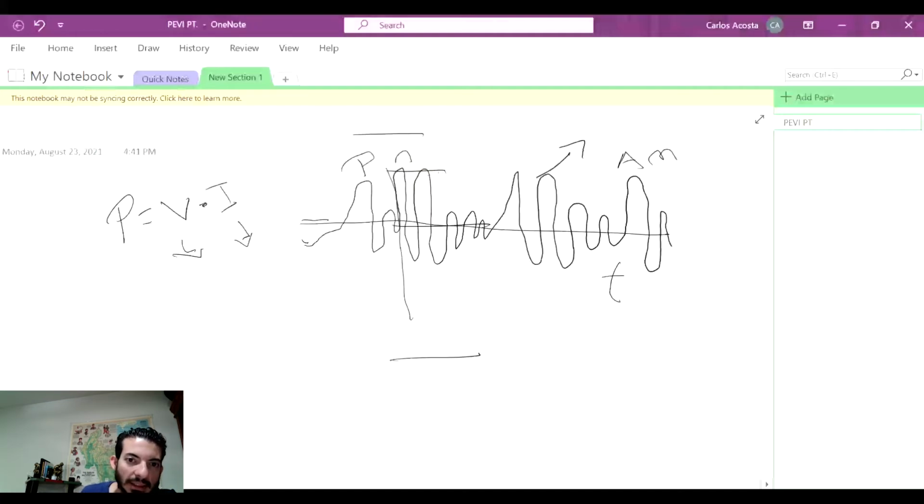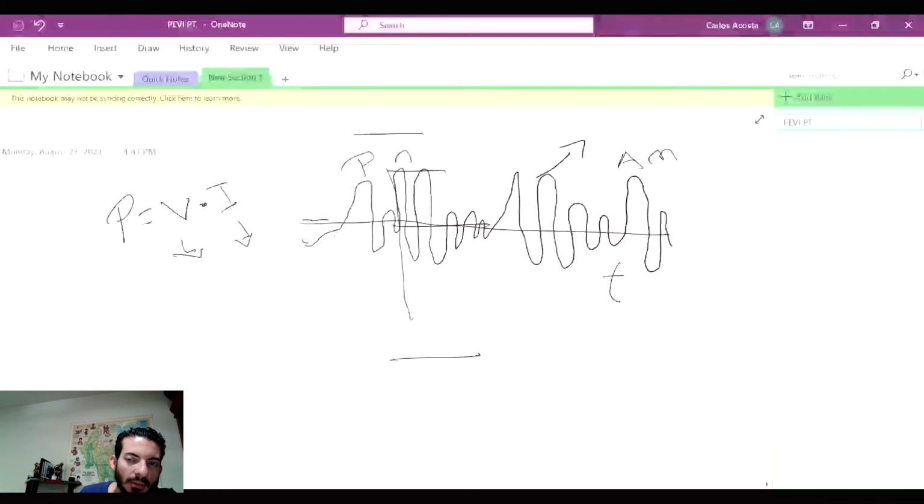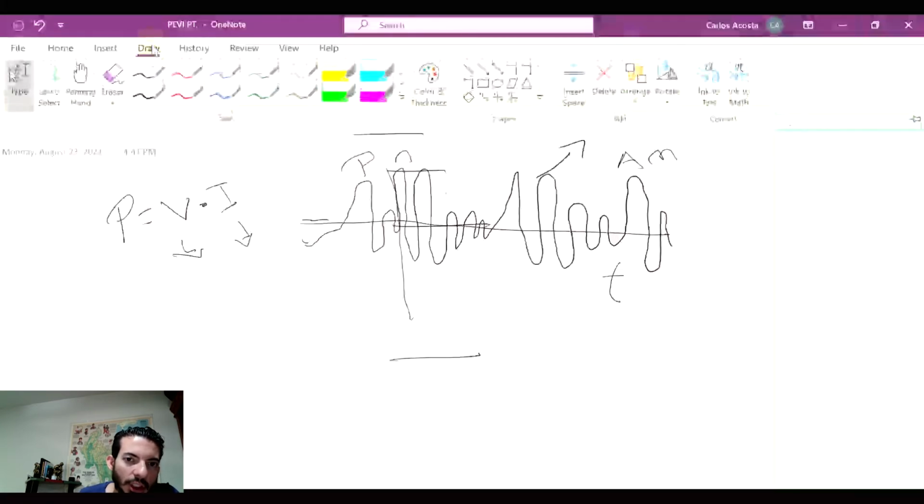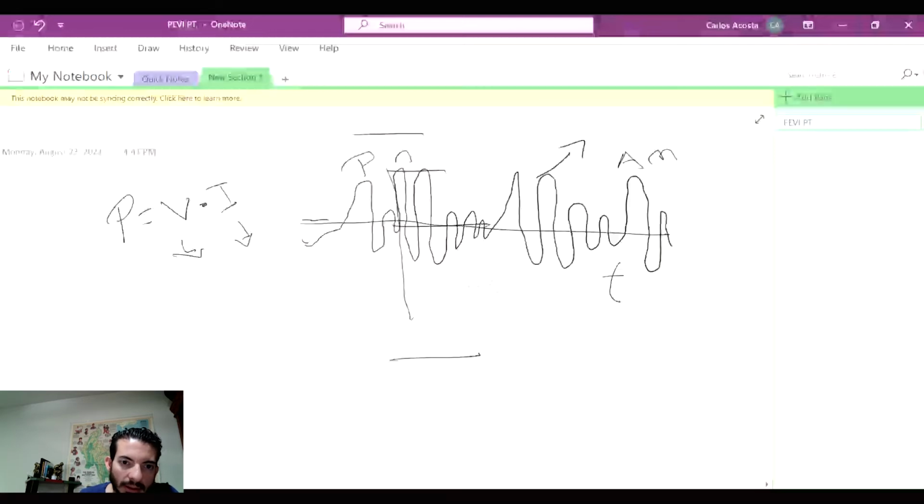So if you're by the station, this looks like that, but if you are far away from the station, then the same signal will look like this. High up here, high up here, high, high, distortion. It's supposed to be the same wave but with more amplitude. The issue here is that this is going to be very noisy, because, as I said, and we'll talk about this later, noise carries on amplitude, not on frequency.